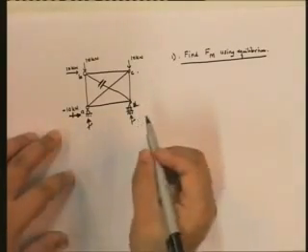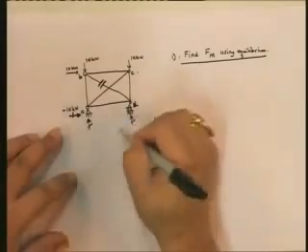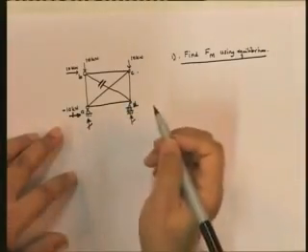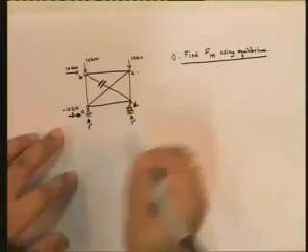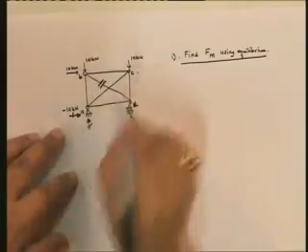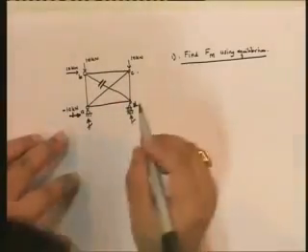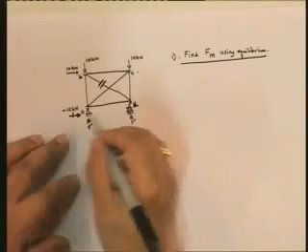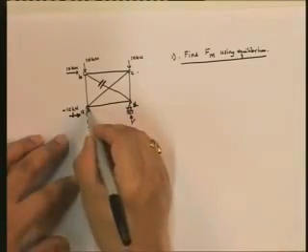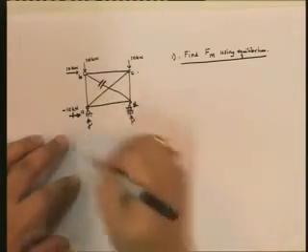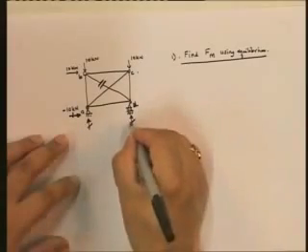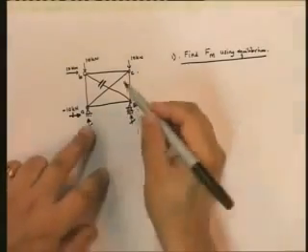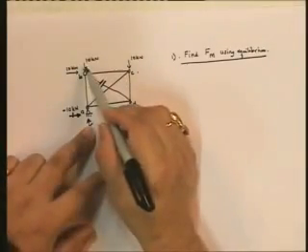Now sigma Fy equal to 0 gives me that this plus this is equal to 20. We know that. However, that still does not help us, so I'm going to take moments about point A of all the forces, and from that I can find this value. Let's look at what the forces are. This does not have any moment.